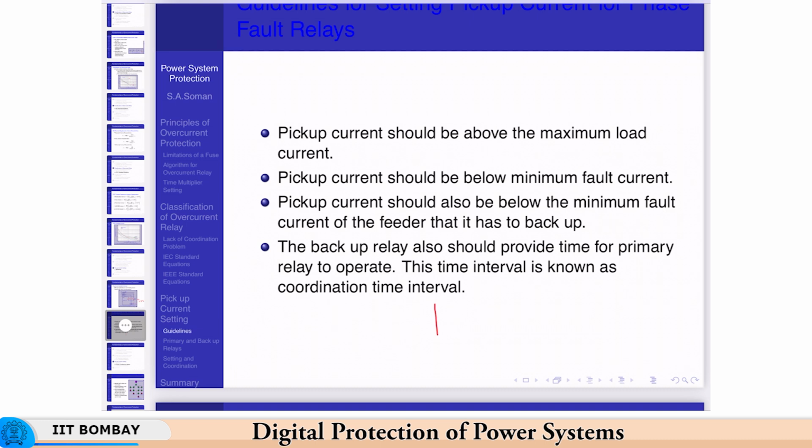Now, the thing to keep in mind is that most electrical equipment are rated for some kind of overload. Usually this is 10%, that is, an equipment which is rated for say 100 amperes can operate at 110 amperes continuously, that is for 24 hours, which is also known as 24-hour rating, or a motor which is rated for 40 kilowatts can operate at 44 kilowatts.